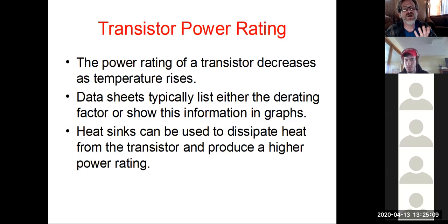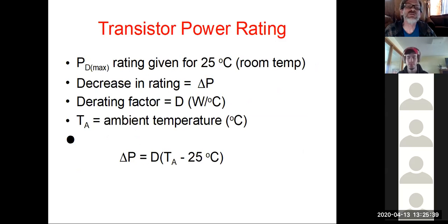But the higher the heat goes, the lower the power rating or the efficiency of your transistor goes. So the data sheet will list what the normal operating temperatures are, and usually it'll show you at higher heats what kind of derating factors you would have to apply. A lot of times you can use heat sinks, and sometimes you'll see some really giant heat sinks with some of these power amplifiers. Excuse me. But okay, next slide, Brenna.